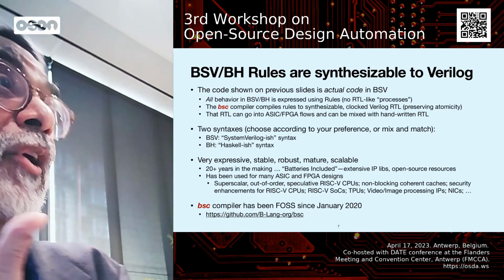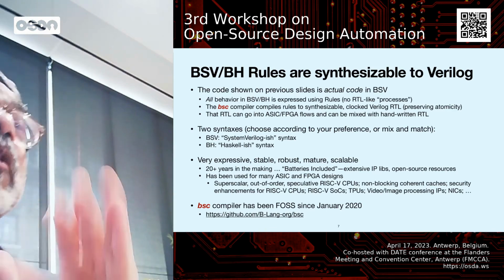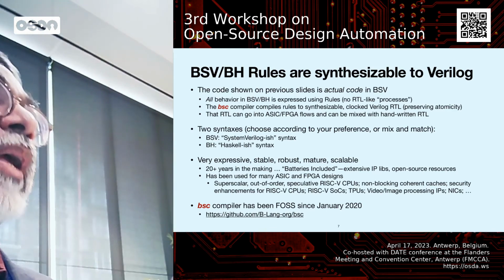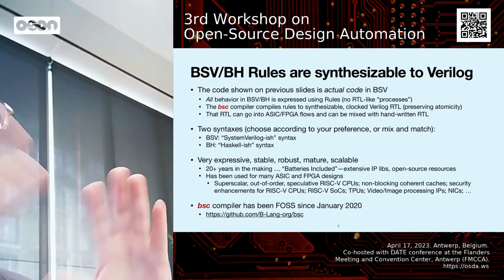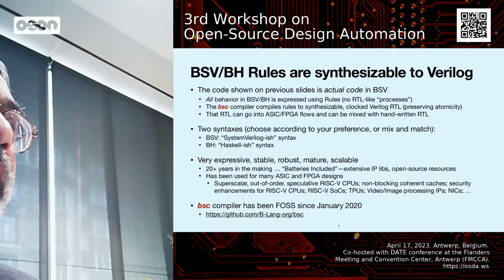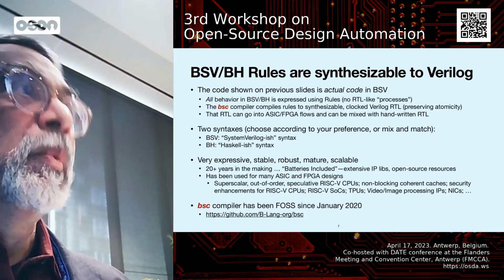I didn't say anything about clocks in any of my description, though ultimately we produce standard clocked synthesizable Verilog. Ultimately it comes down to scalability in your reasoning about correctness. For small circuits, it doesn't make much of a difference whether you use conventional Verilog, SystemVerilog, or BlueSpec. But atomicity is a global property.